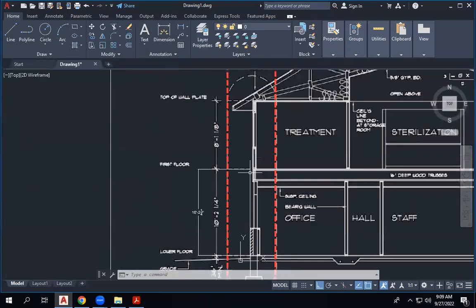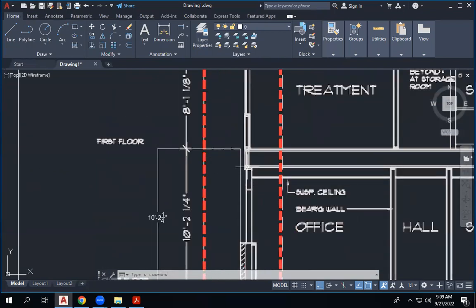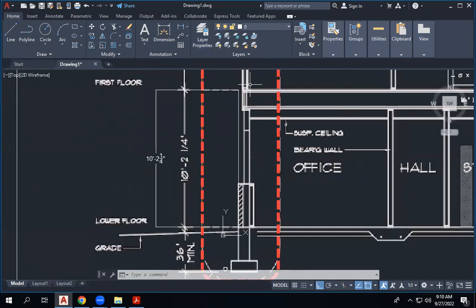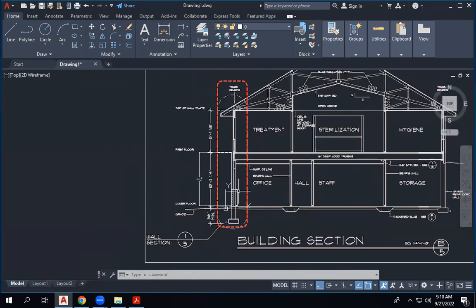Now there might be certain areas in the walls that will be cut. So we will take that one as 0.35. We'll keep one layer for that, 0.35. And any lines just projecting like this, the ceiling will also be cut. You just imagine there is a beam or something here, and something is in elevation. So we will keep 0.1, 0.2 to use for those elements.